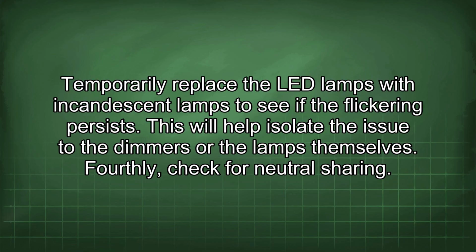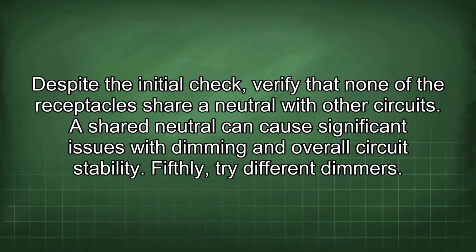Fourthly, check for neutral sharing. Despite the initial check, verify that none of the receptacles share a neutral with other circuits. A shared neutral can cause significant issues with dimming and overall circuit stability.